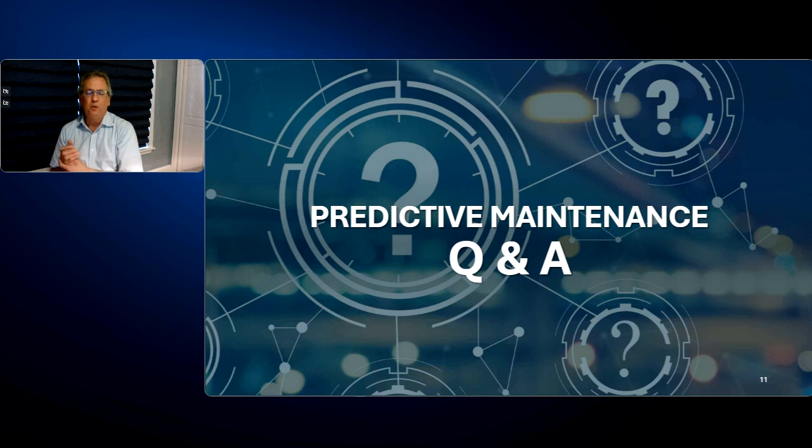this is something we'll talk about more in the fourth webinar. But to answer your question now, it's data. So what has history told us about where the failures have been? Short of data, experience is data, short of classical numbers. So just sitting with the maintenance folks, operators, whoever's been around that equipment for any length of time, getting them to recall past failures, what it was. Oh, we never had problems with the linear slides, but man, those grippers, okay, let's start there.